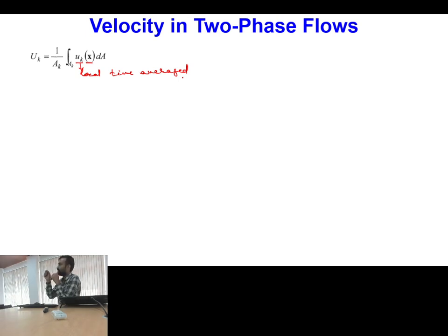Then you measure. So when you are shifting the location of the pitot tube, you are shifting your measurement probe, and at the point at which the measurement probe is located, you are actually measuring your velocity. Though in case of the pitot tube it is not precisely the same point, it is slightly upstream of that point, because in case of the pitot tube, typically at the probe location your flow becomes completely stationary.